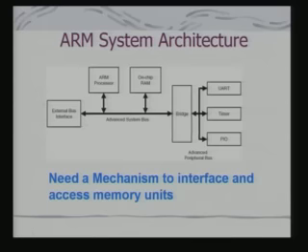This is important even when we are building an SoC, because what do I have? I have this ARM core as a specification, and I know what kind of signals are being provided by the core. So, if I am developing a memory module to be used in my SoC, that memory module has to be compatible with the signals being provided by the processor core.